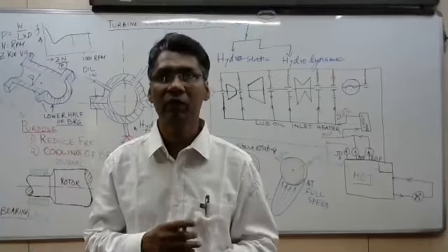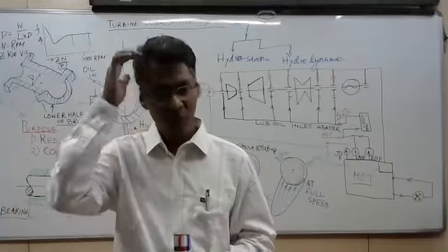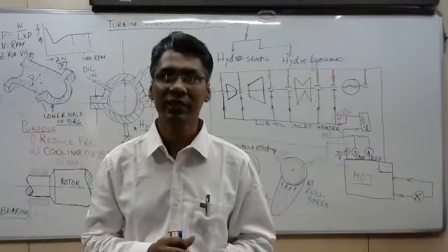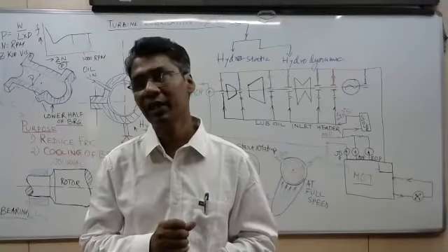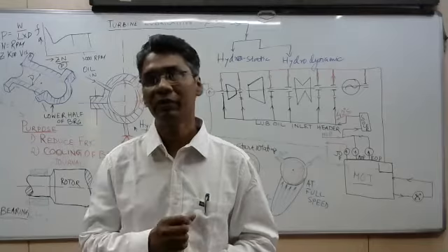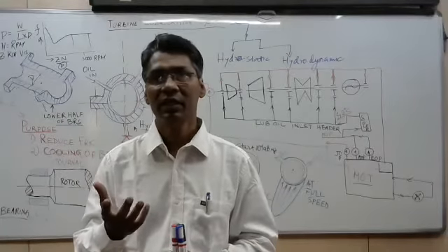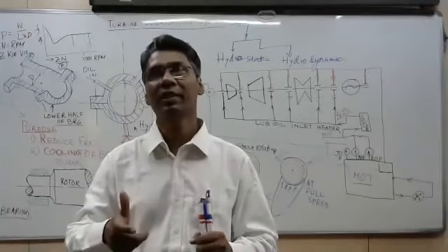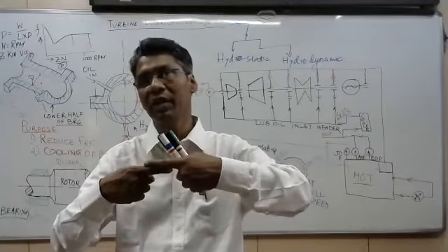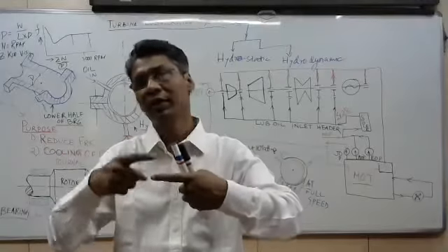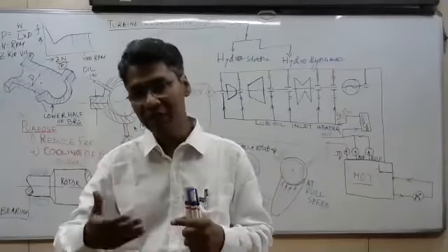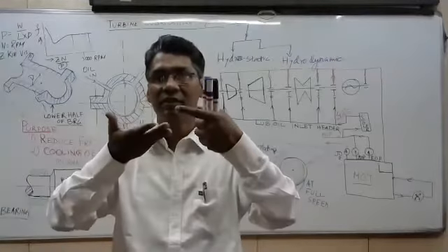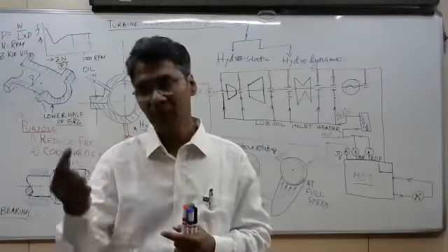And what is a journal bearing, what is a hydrodynamic bearing. Journal bearing has two sorts of system. One is hydrostatic bearing, one is hydrodynamic bearing. By that language you can understand, hydrostatic means at low speed or in static condition, you start rotating the turbine. So initially it is in contact with the bearing. So once you start rotating it with the huge load, the bearing surface will be damaged. So we have to lift the shaft by oil pressure below the bearing surface.